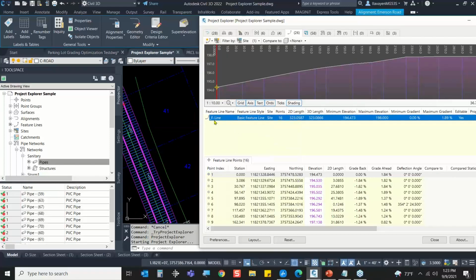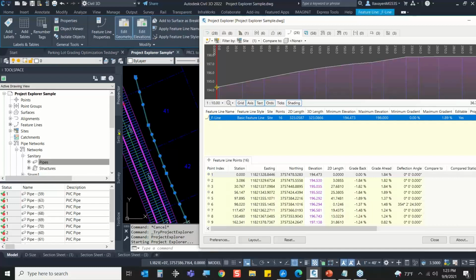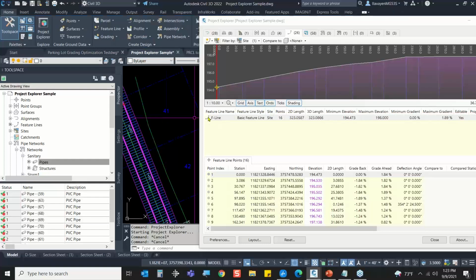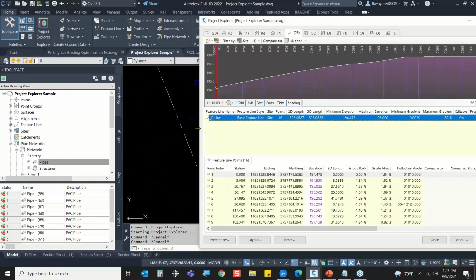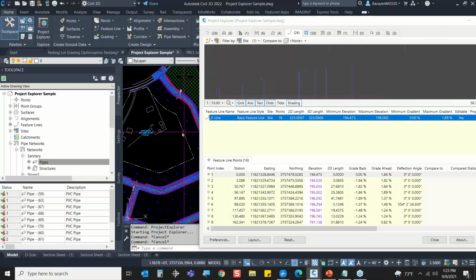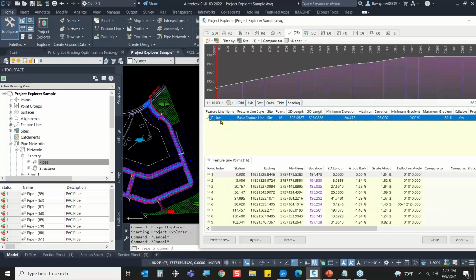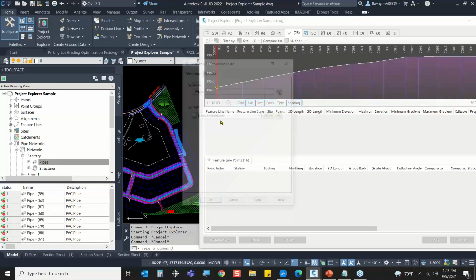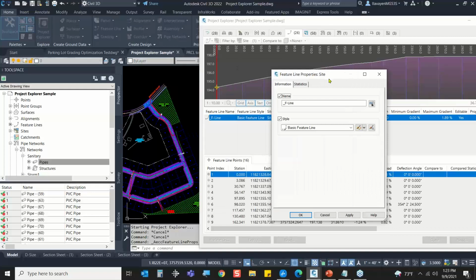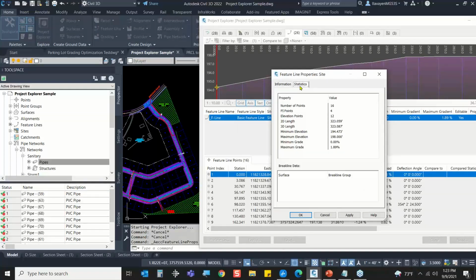And I do have quick keys inside of here. The help bar is really neat. Our blog talks about this. The fact that I can select, highlight, or get into properties, as in I can do S for selection. As I hover, I can do Z to zoom to it, or X to zoom to it. I can start highlighting by using my control key. See how it kind of blinks on there for me? And I can also get into the properties of this element immediately by using the A or the W. So I can get into information a lot quicker to see, to touch, to edit.